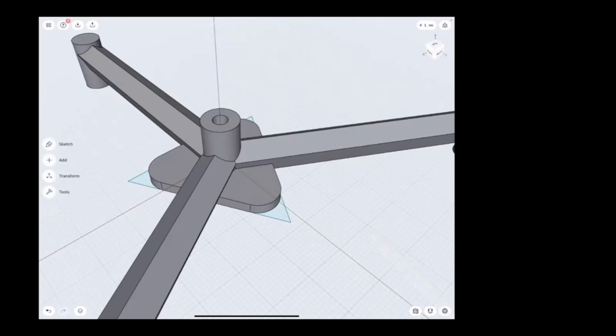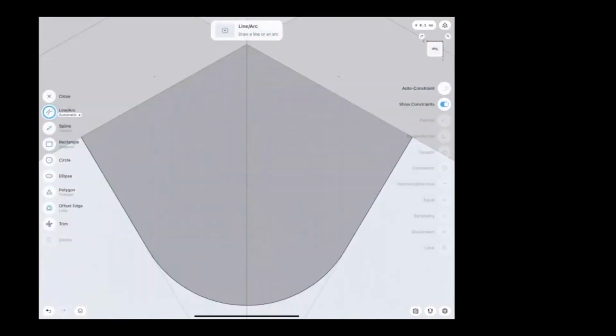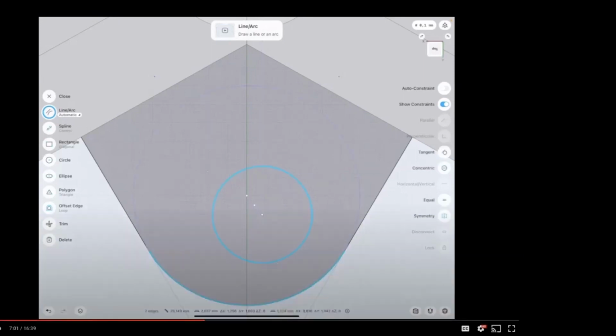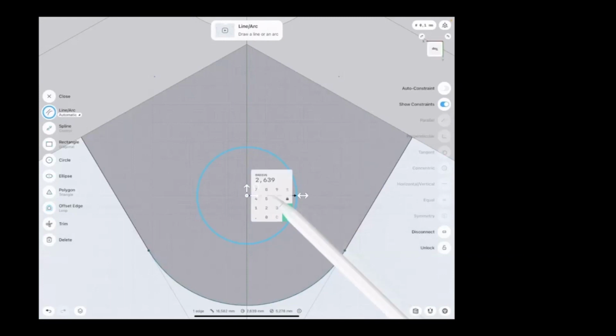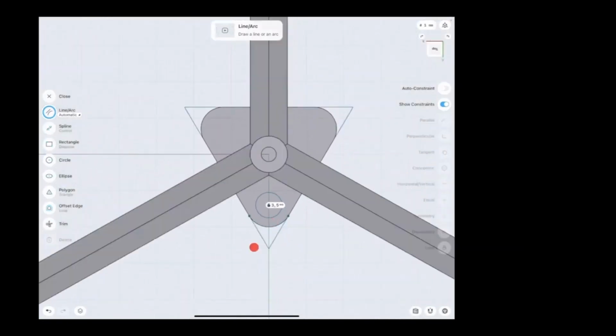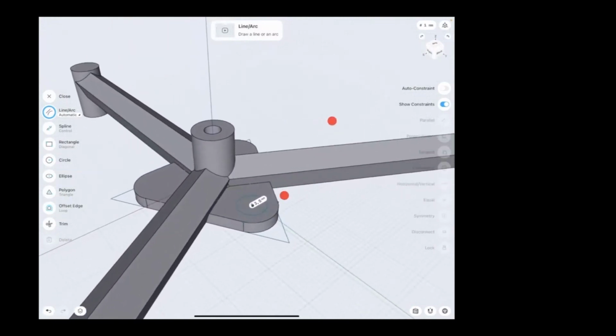Then I can move on with the screw domes. The domes will be simple cylindrical shapes defined on the top surface of this planar body. They should be concentric with the filleted edge with a 3.5 millimeter radius. And I can extrude those upwards by 20 millimeters.